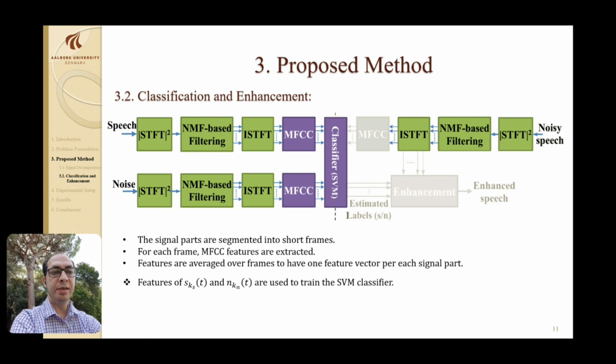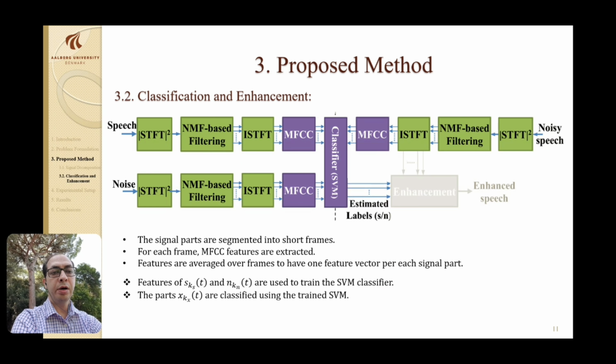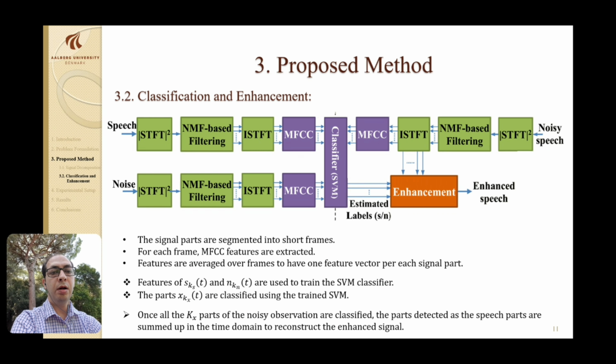During the enhancement phase, the noisy observation is decomposed into signal parts, and we calculate the features from those signal parts, and the parts are classified using the trained SVM. And once all parts of the noisy observation are classified, the parts detected as speech parts are combined in time domain to reconstruct the enhanced signal.